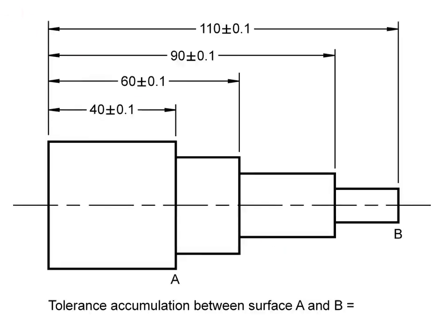From one of the previous chapters, we learned to pick a large surface as our datum. So obviously this has the largest surface. And dimension from there. So we can dimension to our first step from the datum to the first step. Then datum to the second step. Datum to the third step. And finally datum to the final step.